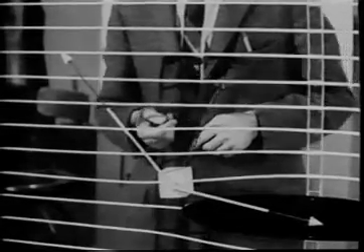For example, suppose that we had a fluid of very small viscosity. Then the viscous forces would be very small compared with the inertial forces. For many practical purposes, then, we might entirely neglect the viscous forces, thus leaving us with a simple balance between the net pressure force and the inertial force.